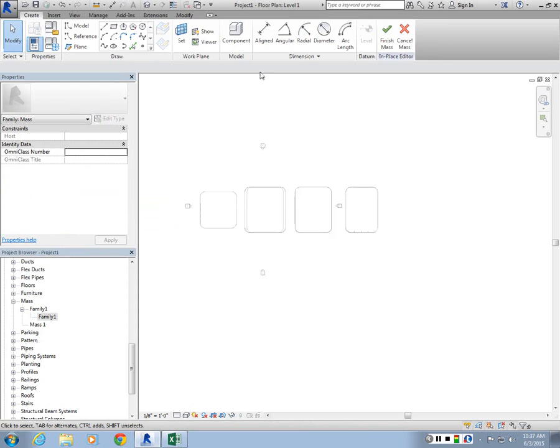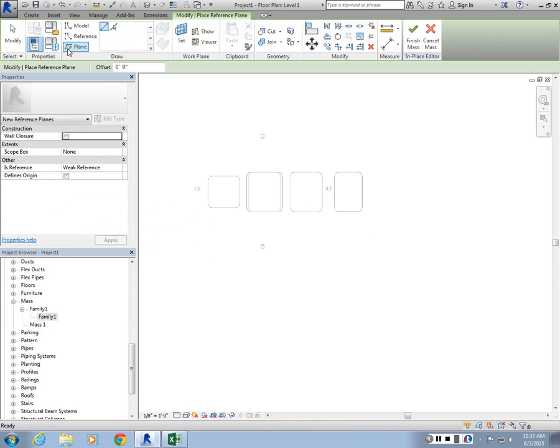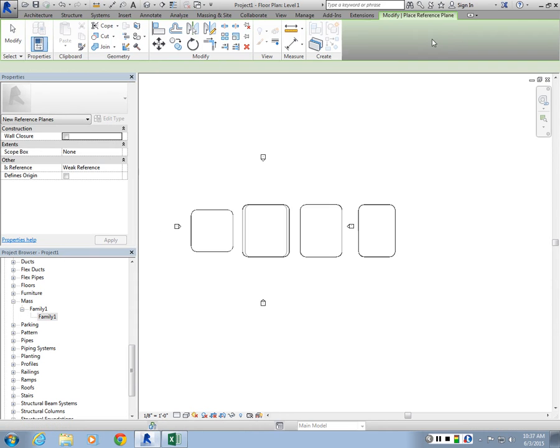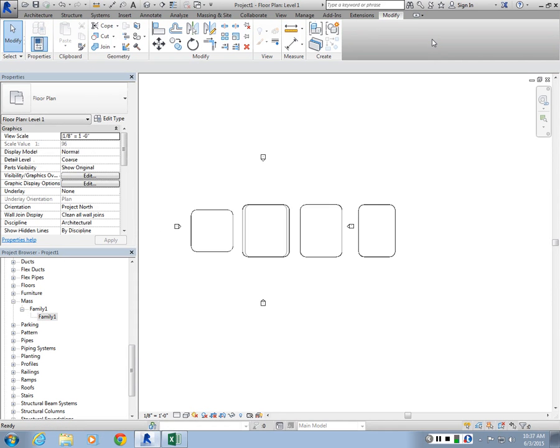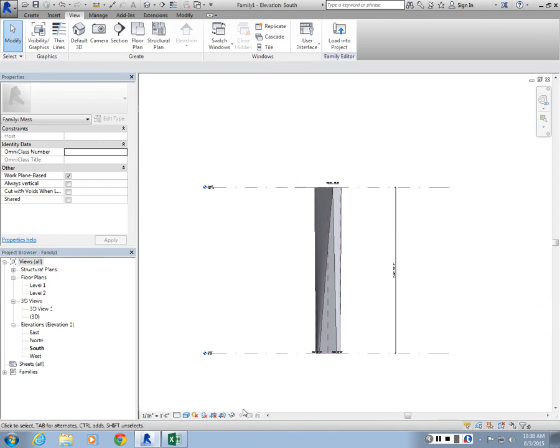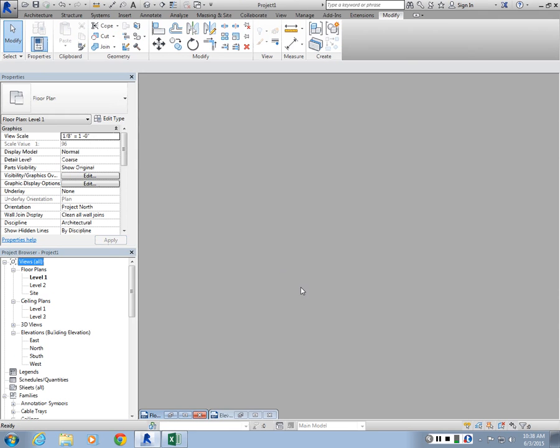So if I do it here, again, I need to set up my reference planes and annotations. It depends on how you want to do it. If you want to just model a quick generic ruled surface, you can do it in the project. It will be easier because you can snap it to existing geometry, right? If there's a building facade here, maybe I can do an example later today, like using the hotel facade to create a secondary surface outside of it using the existing geometry, so that you can see how that works as well. But if you want to do something with constrained dimensions, you can just do it in the massing environment and bring it into the project for use, right?